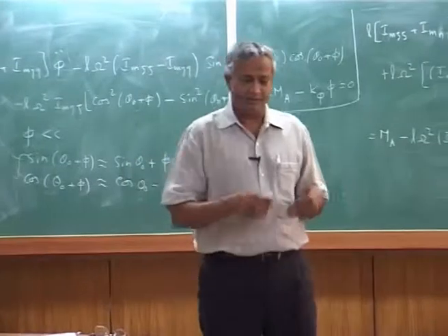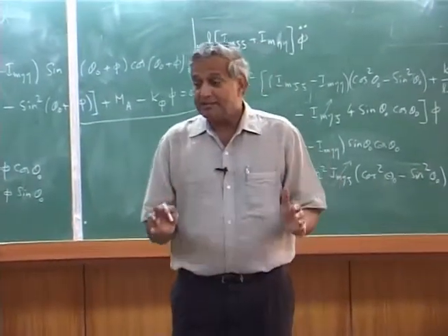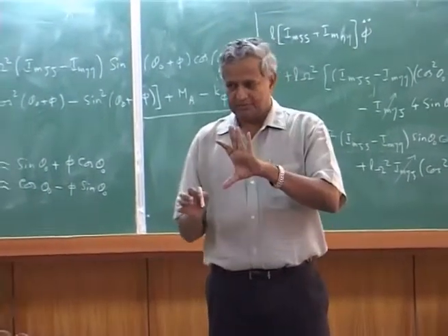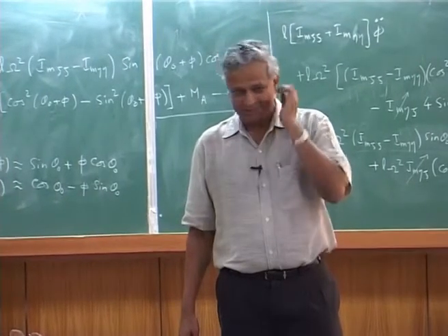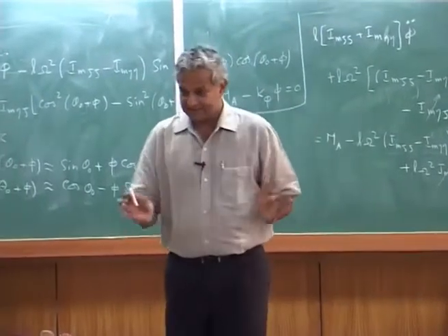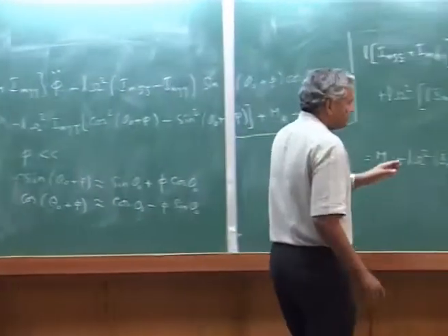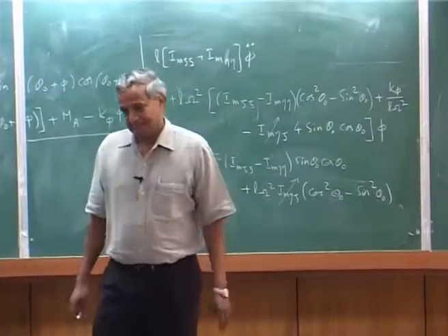You do an FEM model or some approximate calculation, anything, but come up with the stiffness. Usually, of course, control rods are very small, so they are EA over L. But the swash plate will have its own stiffness. Nothing is rigid. So that will give this. There will be a loss in pitch angle.